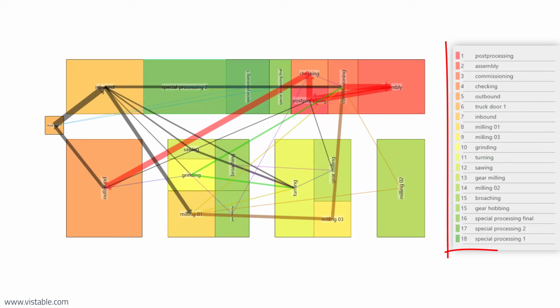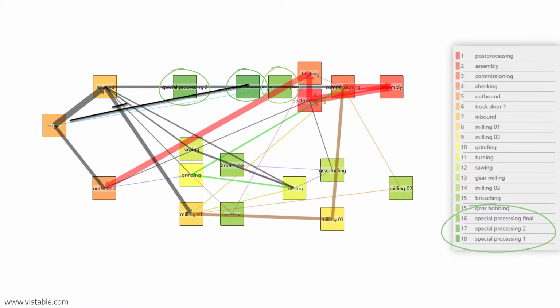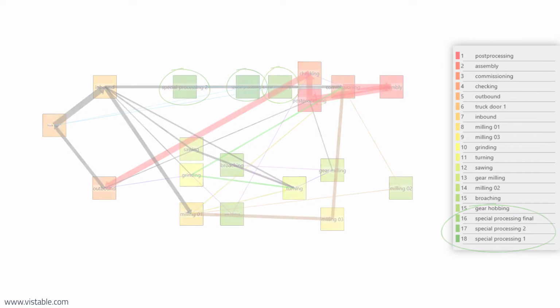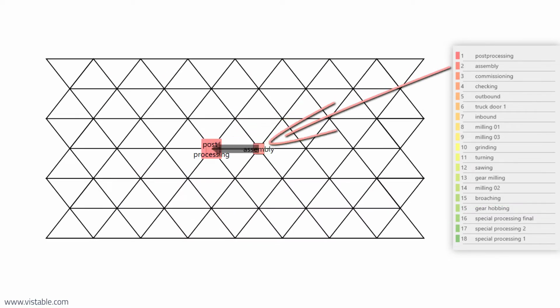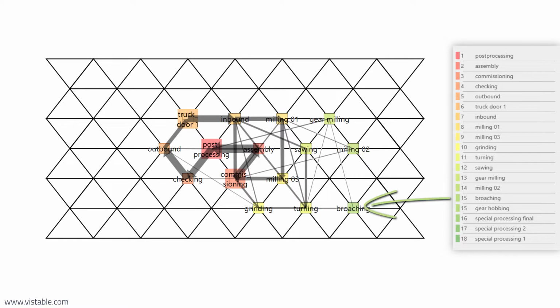Here, we see a procedure that shows an arrangement priority for a network structure. The objects with high priority are strongly integrated into the material flow. Objects with low priority have only weak material flow connections. The idea of this procedure is to arrange the objects with high priority centrally first, and then to place objects with low priority further outside. This should lead to good planning solutions.